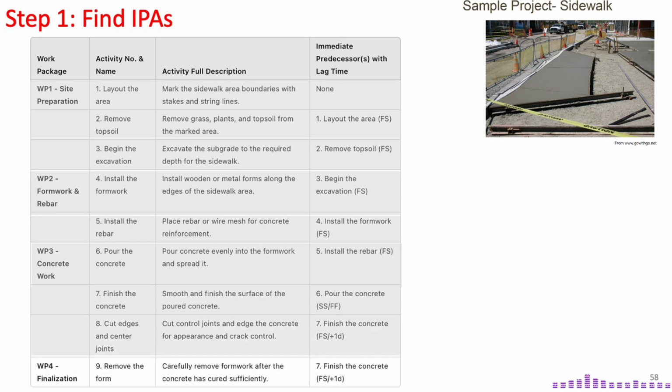The forms are taken off once the concrete gains strength. This also depends on the completion of concrete finishing and some curing. Hence, activity 7 is the immediate predecessor, also connected with FS logic and a 1-day lag.